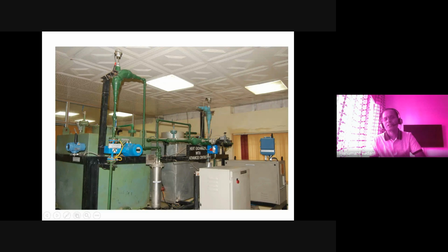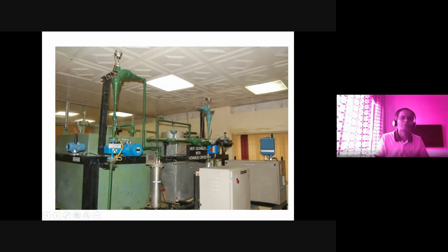This is a rotameter transmitter. This rotameter works on a magnetic principle, not like a float. It is a magnetic principle based rotameter. And then among the other instruments, you can see a wireless temperature transmitter here, and this temperature transmitter is getting input from this RTD.